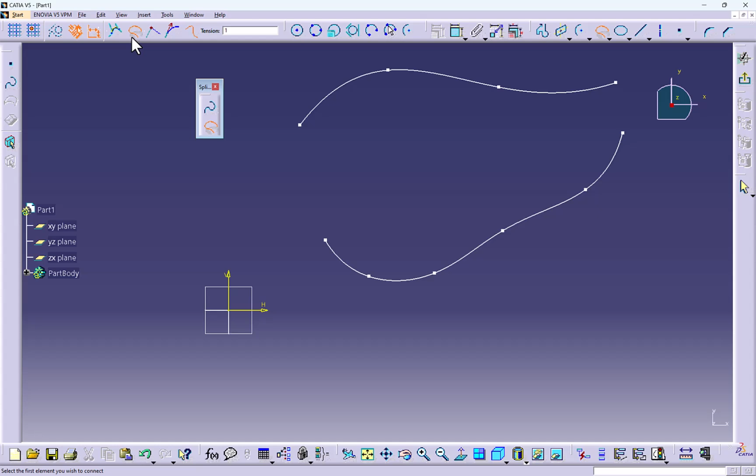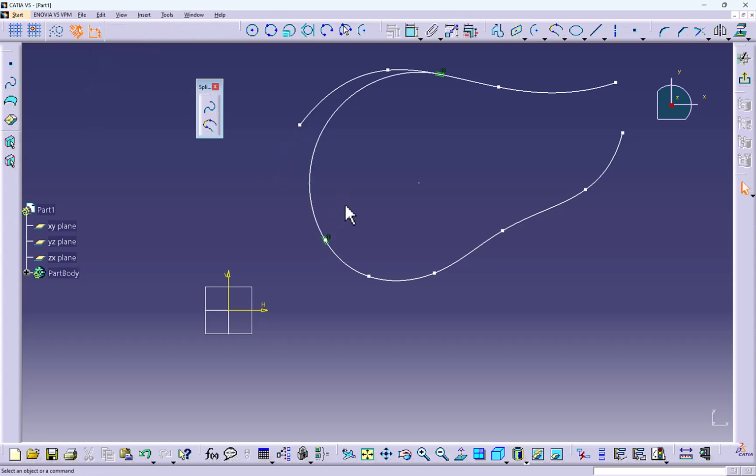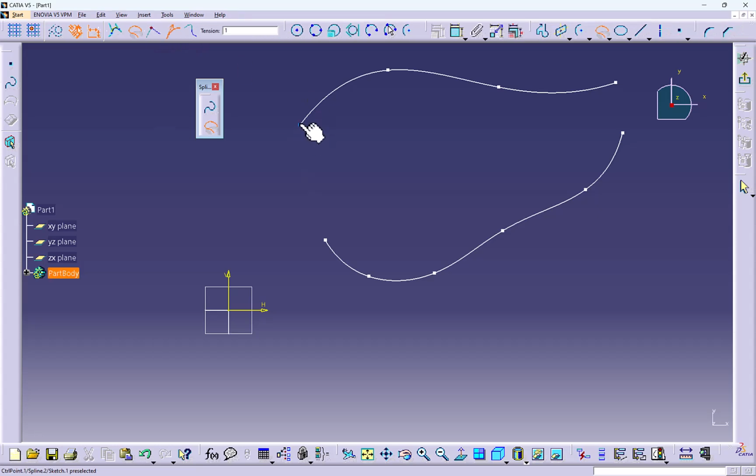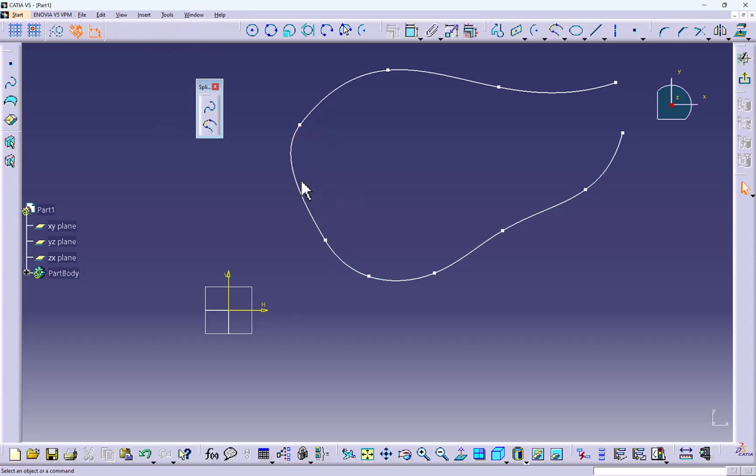Okay. We have more things in this. We can take this option from here. We want to take like an arc. We can add an arc here. Like this, we'll try to add a tangency arc. Then if we want to add a line or something with a point, we can just take a point, the straight line. Then we can also take some continuity tangency. We can select that and we can try to maintain a continuity tangency.